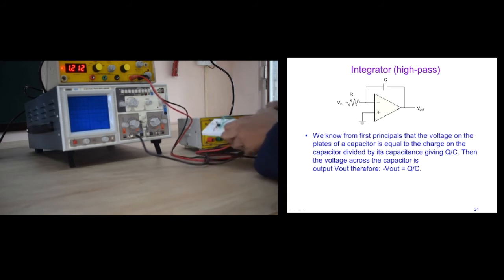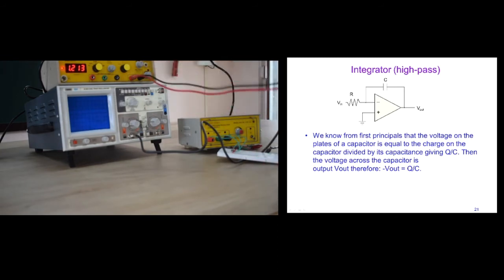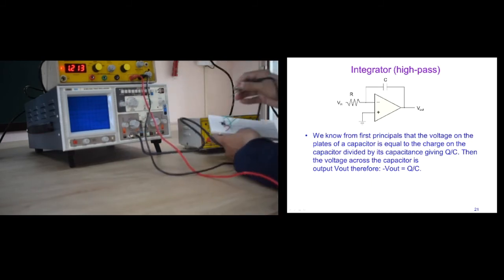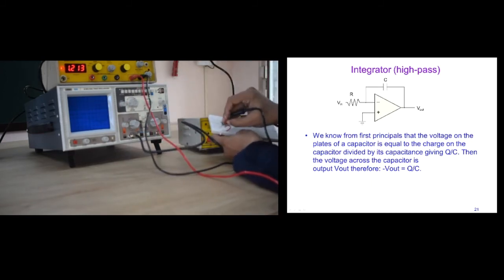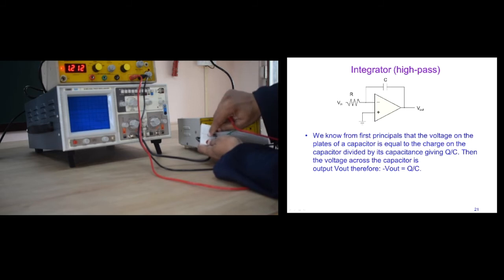Now we will connect black and red of the signal generator to the circuitry. The black always goes to the ground, so we will connect this black terminal to the horizontal line where we are connecting every ground of the circuit, and the remaining red terminal we will connect to the resistance input R in. Yes, we have connected the resistor R in to the signal generator.